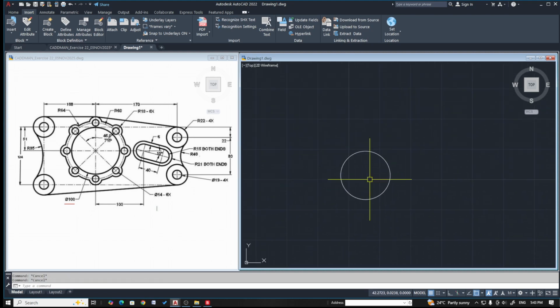and then I'll try to create a center line from here to here and here to here, and let's try to lengthen these lines by giving lengthen, DE, delta, to a distance of 20 on all the sides. So that's my center actually. So let's not change the solid lines to center lines right now.